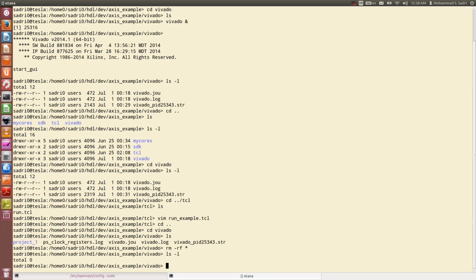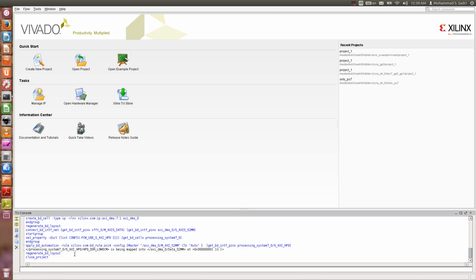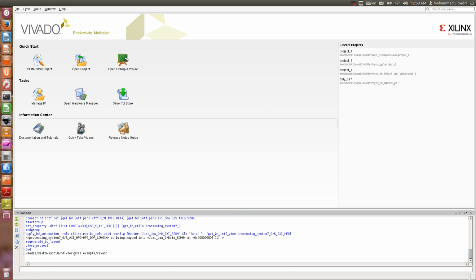Now I come back here to the Vivado environment and I have the TCL console here, and inside the TCL console I call my TCL script. So let's say pwd, where am I? I'm here, source is here, inside run example.tcl, enter.